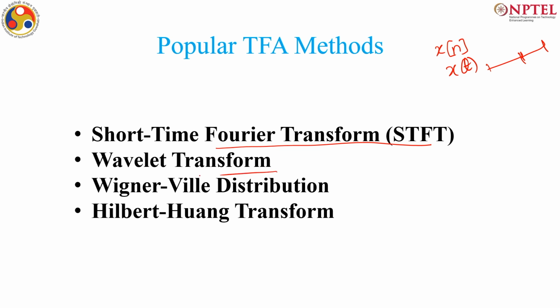What about wavelet transform? Wavelet transform extends this idea to non-sinusoidal basis, like if I have a signal which has a sharp change like this. So, probably if I use sinusoid, it might not be very convenient and it may take a lot of coefficients or a lot of components to approximate this signal. But rather if I analyze this kind of signal with a sharp kind of a small module or basic signal which I call wavelet, then this will be easier and faster to analyze.